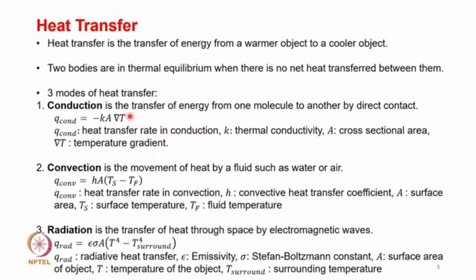The heat conduction equation says that heat transfer is directly proportional to the temperature gradient: Q conduction is equal to minus K A delta T, where delta T is the temperature gradient, K is the thermal conductivity, Q is the heat transfer rate in conduction, and of course A is the cross sectional area.